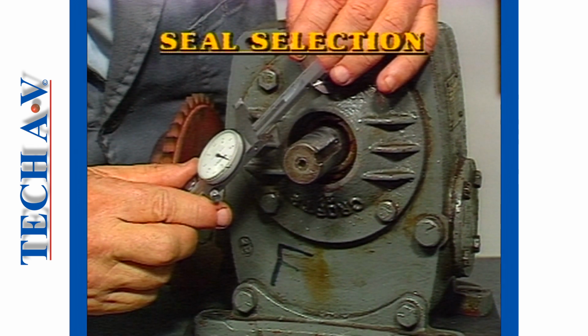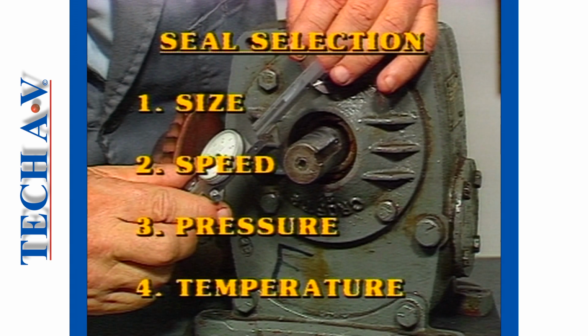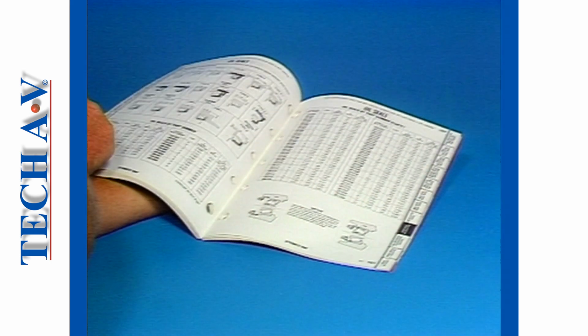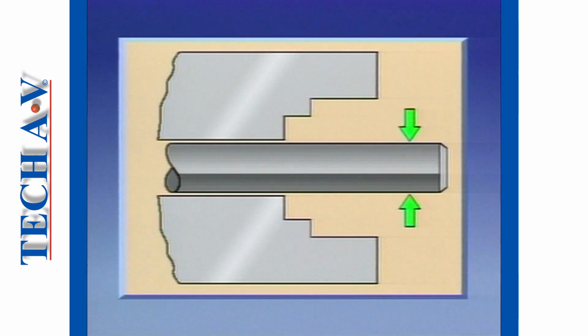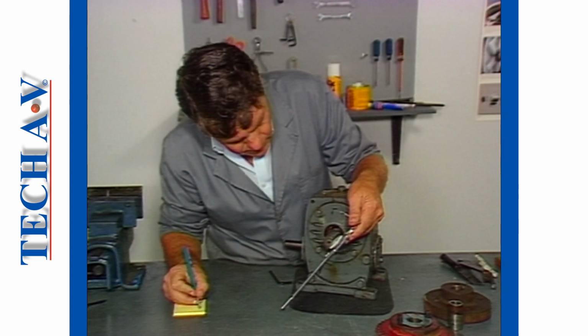There are basically 4 considerations to make, namely, the size of the seal, the shaft speed, pressure against the seal, and temperature of operation. Let us first consider the size of a seal. Seal descriptions relate to 3 dimensions, namely the shaft diameter, the seal housing or bore diameter, and the depth of the seal housing. All dimensions are given in millimeters. If you supply such information, then a suitable seal size can be obtained from your local supplier.